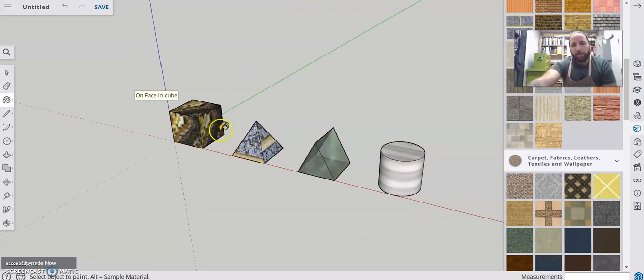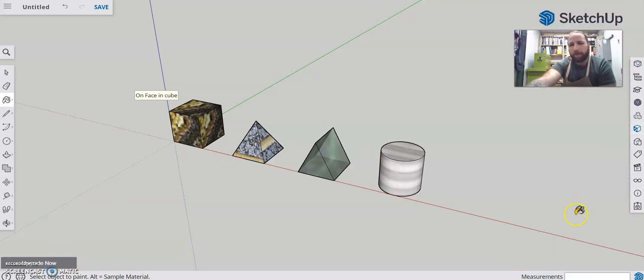first tutorial. 4 shapes. Make sure, absolutely make sure that those are components because that's the best habit to get into. You really, really do want to get into the habit of making sure that anything you make is a component. It will save you so many headaches as you work in SketchUp. So that's the end. Try it out. This next tutorial we'll get into modeling some things that we'll actually build.